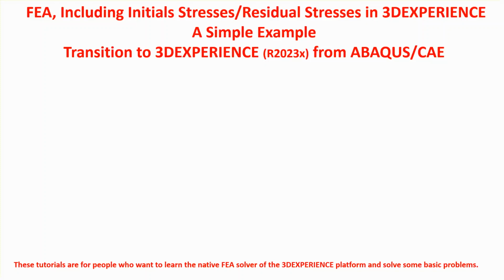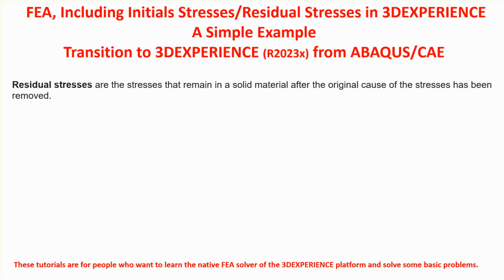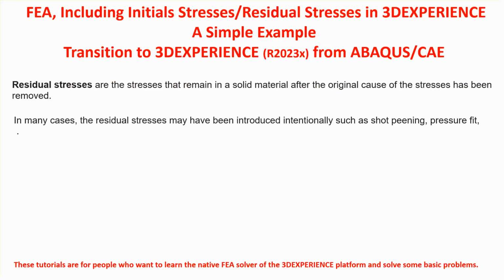Now, let me say a few words about this business of residual or initial stresses. There are stresses that get locked into the body after the source of that stress has been removed. Now, these stresses may be introduced intentionally. For example, when you're doing a shrink fit, you take a shaft that has a bigger diameter than the bearing, and maybe heat up the bearing so that it expands, and then put the shaft in it, and then let it